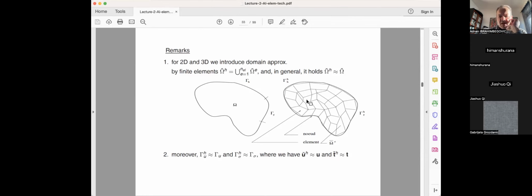Anyway, we'll stick to our polynomials and explain that, because the vast majority of computer codes are using that. So basically we'll have to learn how to construct the interpolation over the typical triangle elements, quadrilateral elements, and so on as we go along. So we split that from the element point of view, and then build it together with the element type of computation, what we call finite element technology. At the end, we'll do the assembly and recover the whole thing.